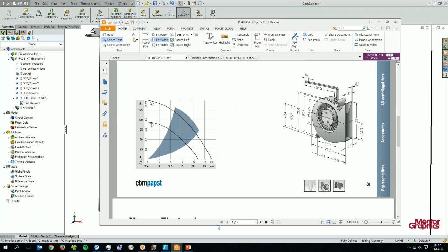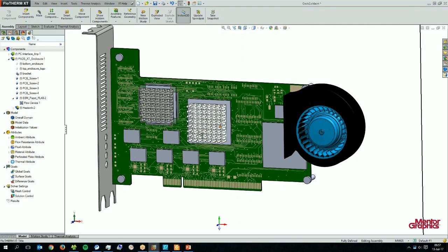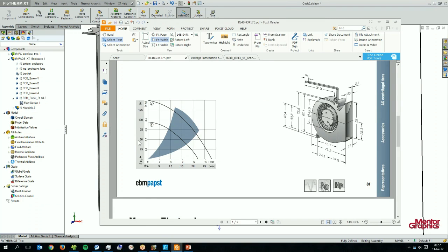And this will depend on how much fluidic resistance there is downstream to the airflow. So the air having to fight through heat sinks, having to go through vents, this is all going to be causing a pressure drop and a back pressure onto the fan, and depending on what back pressure the fan sees, it's going to blow at a certain rate on this particular curve.